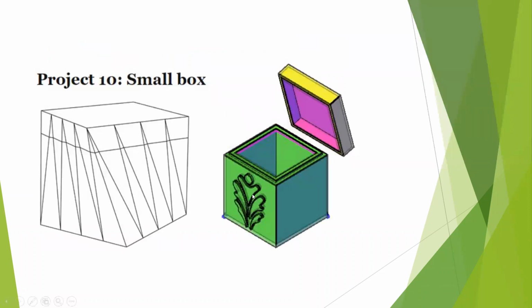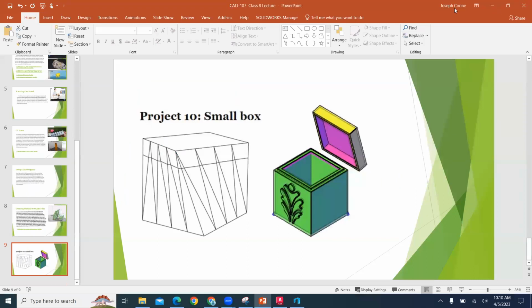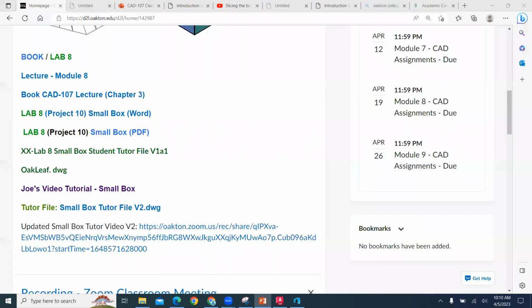But for right now, we're using inserts. We can go ahead and design this and then use Boolean applications to subtract the geometry for that, and then print them in a different color and insert it, and it works great. And so from that standpoint, you're not going to do everything on the 3D printer. You're going to have some post-processing.